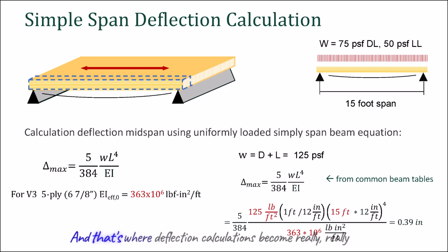That is absolutely critical, and that's where deflection calculations become really, really important. Even if a panel is super strong, too much sag, too much deflection can cause problems. Aesthetic issues, problems with floor finishes, or, like you said, just making people feel uneasy. Right. Nobody wants a floor that feels like a trampoline unless it is one.